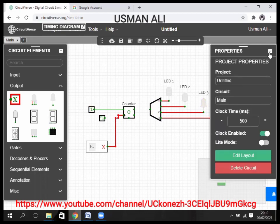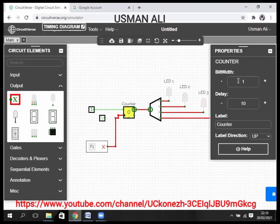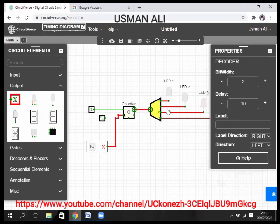You see our four LED lights are placed here. Now, when you connect our counter to the decoder, you see here is a bit width error. We click here, disconnect it, then connect it again. You see here bit width error 1 and 2, because our counter bit width is 1 and our decoder bit width is 2. Because of that, our circuit is giving an error.